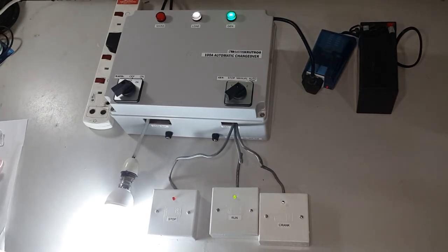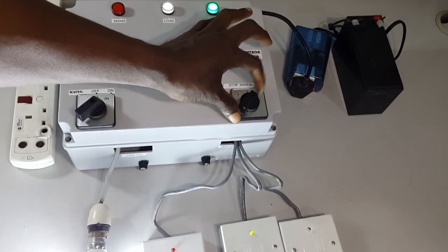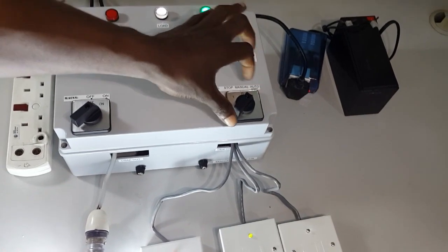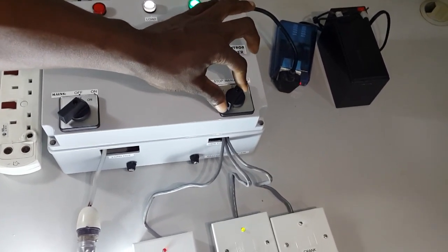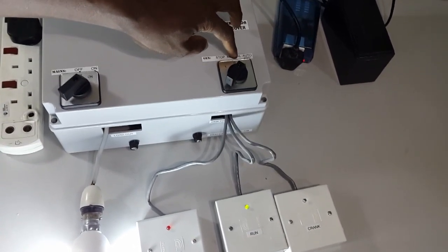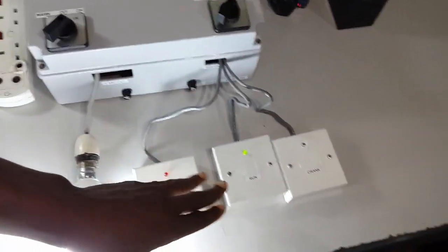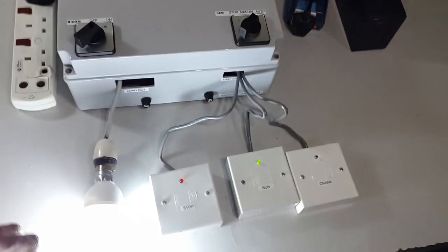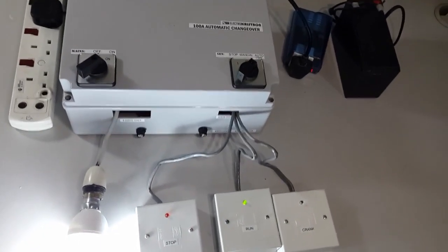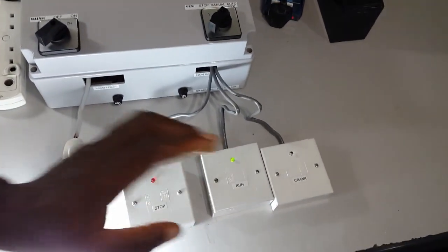manually. There are two ways. Either you go and turn off the gen directly at the generator house, or you can turn it off right from here by moving the switch from the AutoStart position to the manual position or to the stop position. Whether you use the manual position or the stop position to turn your gen off will depend on the type of generator configuration and ignition system your generator has. But in this case, let us just imagine that your gen has the run function only.